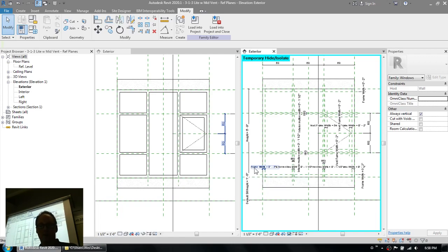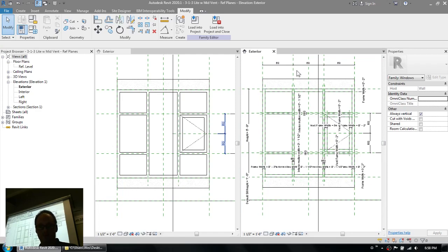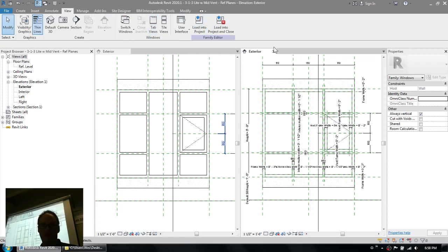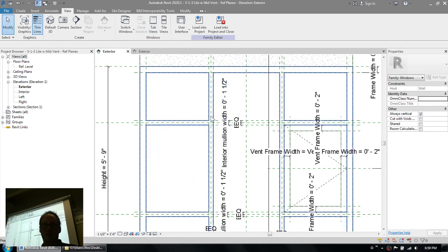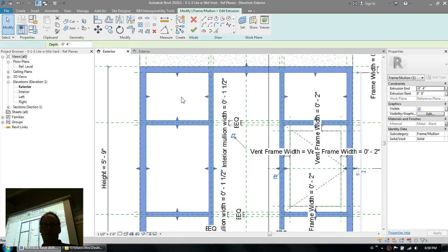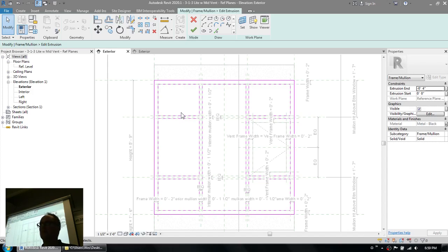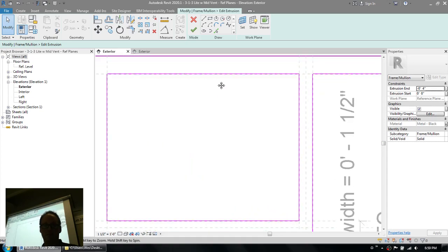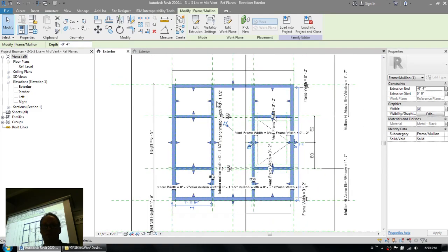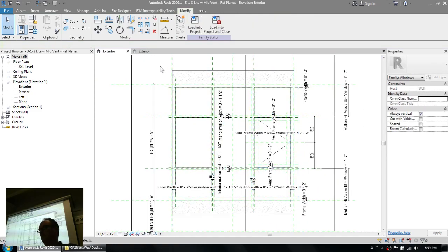So when I went to build these, let me just go back to the tabbed mode here. When I went back to building these geometries, when I look at these geometries and what's inside them, there are no dimensions, because the sketch lines that you see here are locked back to the reference planes that were already there before I started building this extrusion. So what's the real difference? Well, they both behave exactly the same way. One just has more reference planes in it, and you folks can decide which approach is better.